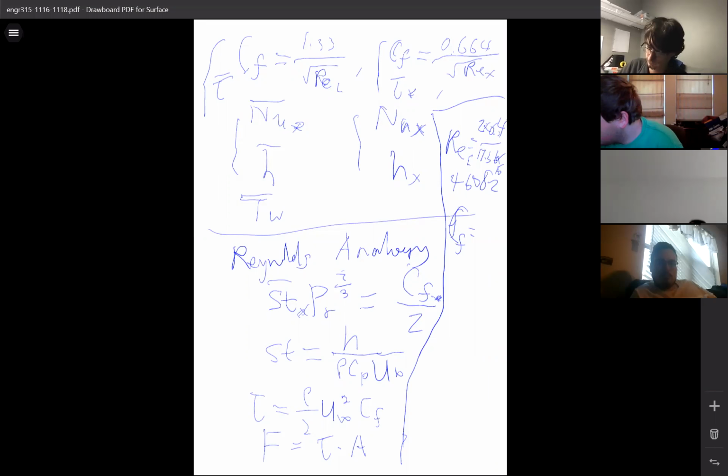Quick question, Dr. Sang. Do we not multiply by rho or anything on the Reynolds number or no? Reynolds number, you mean? Depends on which viscosity you're using. This is the kinematic viscosity. If you use dynamic viscosity mu, then you have to have a rho in the top. Okay, got you, sir. Be careful. That's the point.